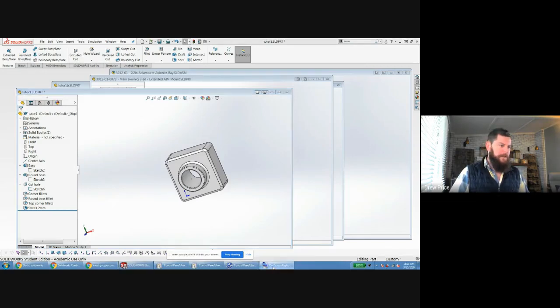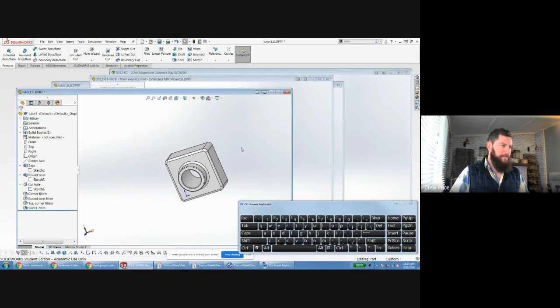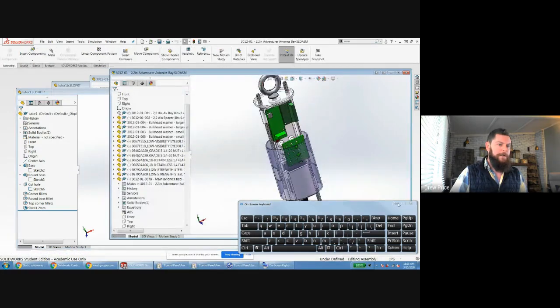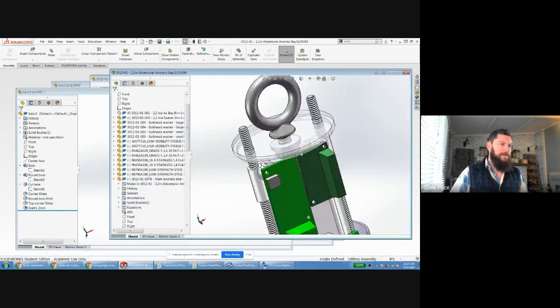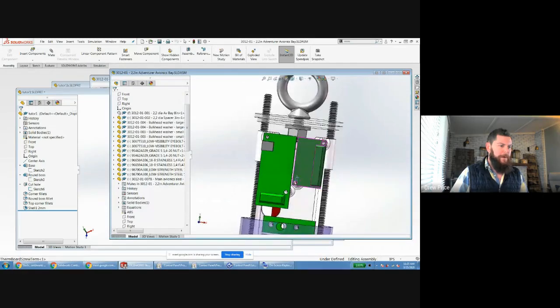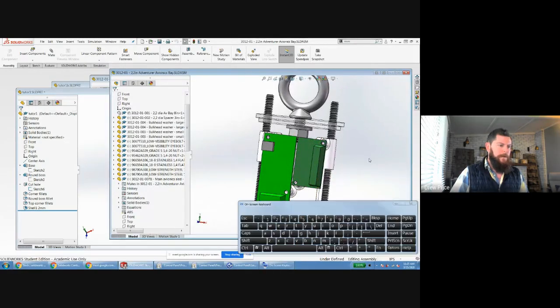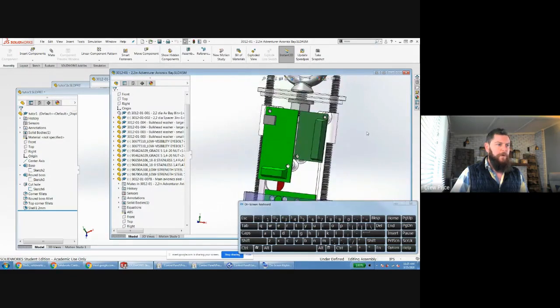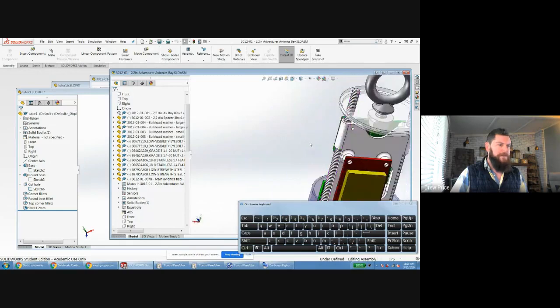The next thing, if I pull this keyboard up here, so if I'm within my model, if I just press on the scroll wheel and drag around, it'll rotate my part. If I hold Control while I press on the scroll wheel and drag the mouse around, it'll pan my part around. So that's also convenient for maybe larger or more complicated assemblies where you might want to be only looking at this side of a part during an inspection. It'll let me slide the part up within my view without moving it around rather than just rotating it like that.